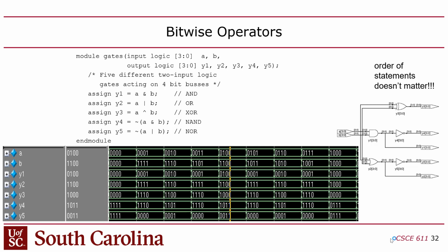Yeah, well, so one of the things we're going to do later is we're going to create a RAM. A RAM is like a 2D array because there's a width and a height. And this even gets more confusing because in a RAM, you put the width first, and then you put brackets after the name to create the depth, the number of entries in the RAM, which is even crazier.